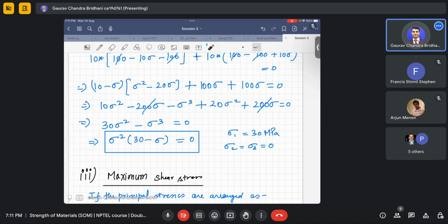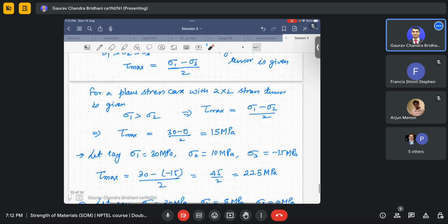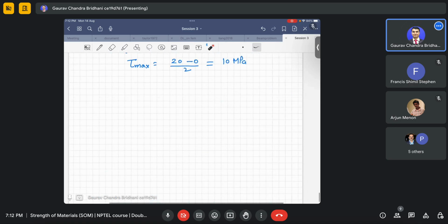It will be calculated from the bigger circle, and the bigger circle will be drawn only when the points are most far apart. Those points on the horizontal axis of the bigger circle are sigma 1 and sigma 3 actually. Okay, and sigma 2 lies in between. I'll draw it here. If I draw, you will remember and understand what I'm trying to say.